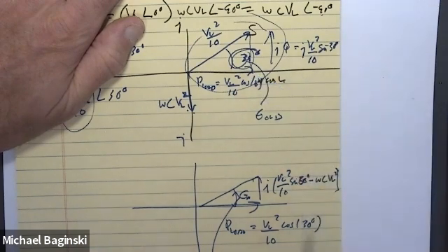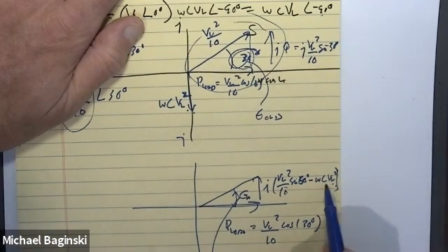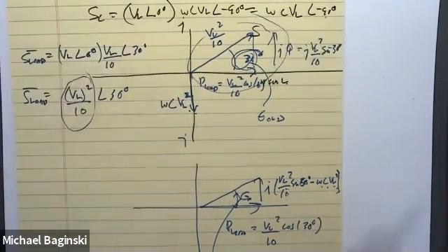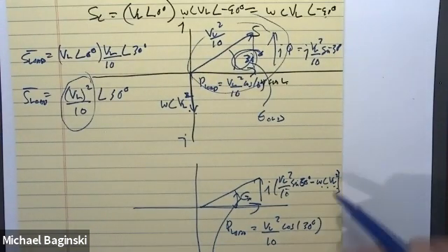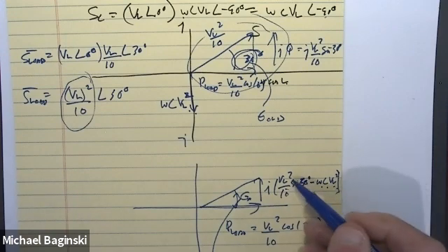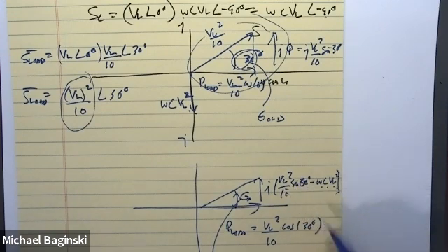And if we adjust this capacitor, if we make this have a net value of 0, then we would have strictly real power, no reactive power. Do you follow me on that? All right. If, in fact, we allow that capacitor, remember, this is subtracting from this. If we allow the omega C VL squared to be equal to VL squared over 10 sine of 30, then we would have 0 reactive power. You follow me on that, class?